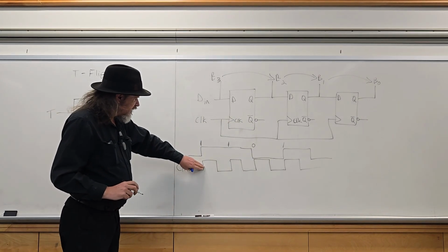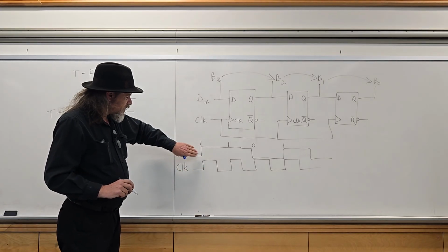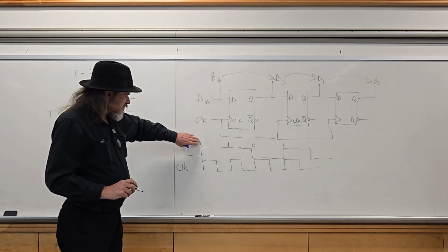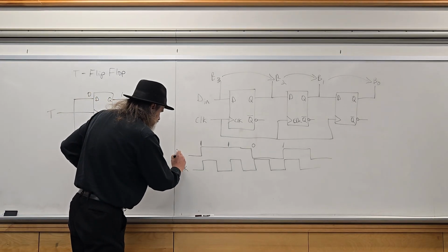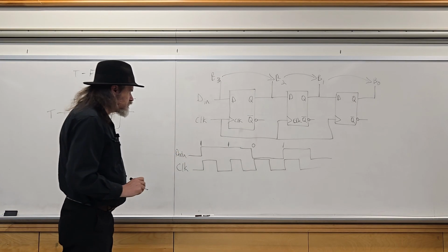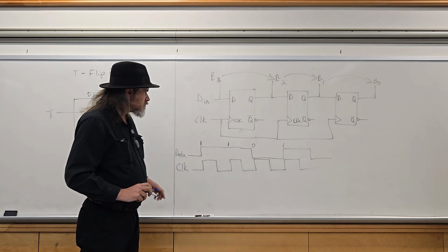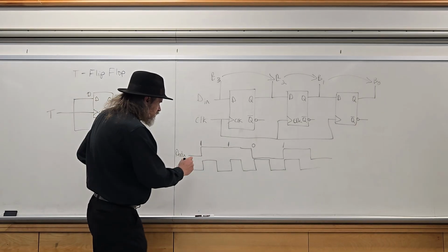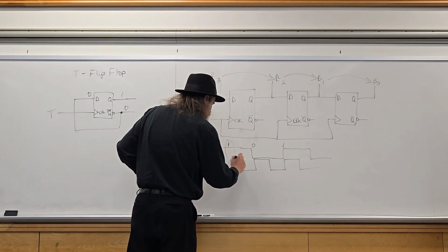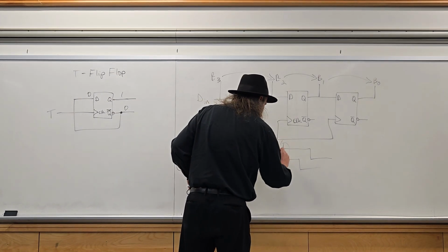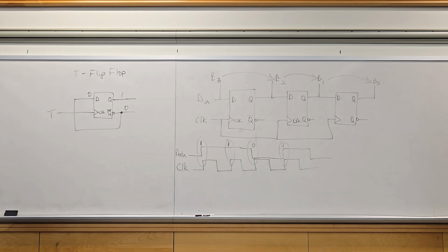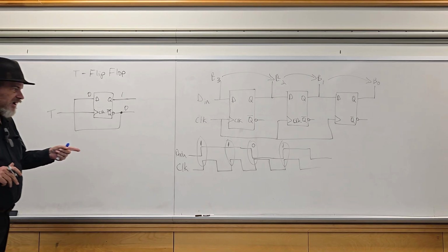So when the clock goes on a rising edge, it reads the value on the data line. It reads the level there. So you read here, you read here, you read here, you read here. That's how a serial signal works. You have 2 lines. You have your data line and your clock line.